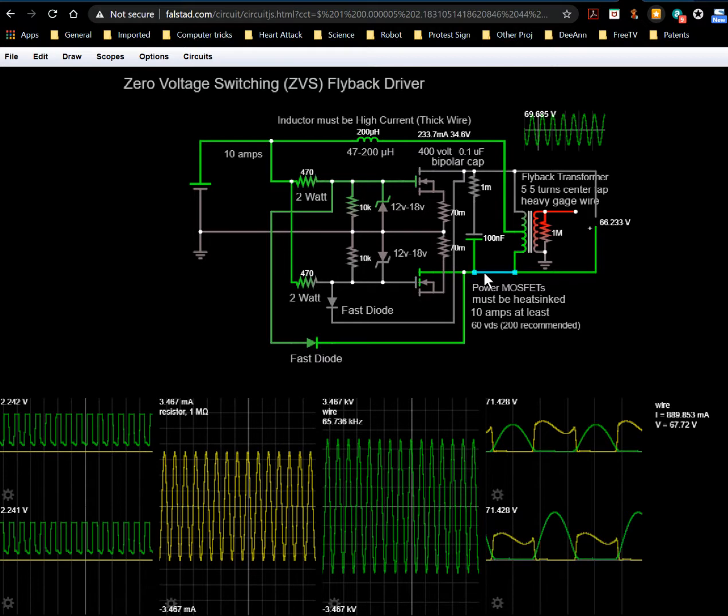So that's why this voltage is 67 volts as opposed to this voltage being 1.4 volts, because this is on, making a low resistance path, like 70 milliohms. Although in practice it probably won't be exactly that, at any rate it makes a low resistance path to ground. But because we have these diodes connecting up the two, this voltage controls this transistor's gate voltage, and this one's voltage controls this transistor's gate.